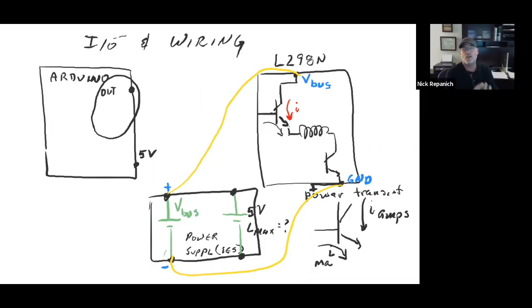If you hook up your air compressor and run it off the circuit, I did this one time. I was trying to run a 0.5 horsepower air compressor off of a 3 horsepower generator. No problem, you would think, right? 3 horsepower generator, 0.5 horsepower motor, except it's an inductive load. You plug it in and turn it on, and it goes "Bruh," because that inductive load draws a ton of current right at first that the generator can't supply.